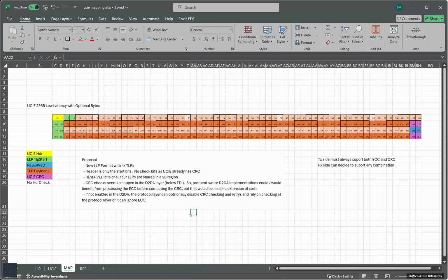the ECC, because UCIe doesn't have registers there. They just do everything through wires, right? So basically it would be a single wire signifying ECC, or we would define a new flit type, and that flit type would also include that, part of our link layer processing.